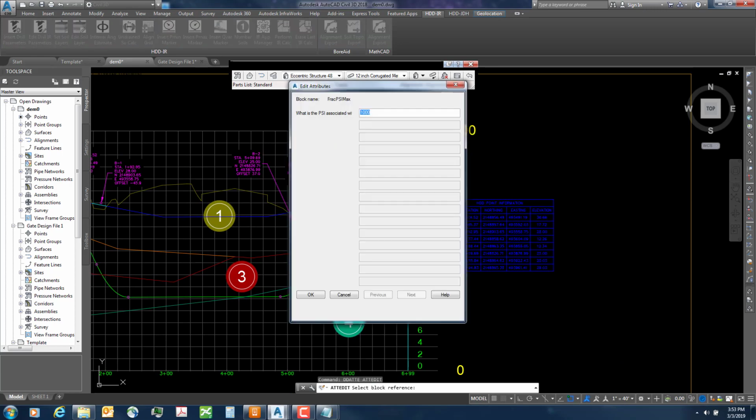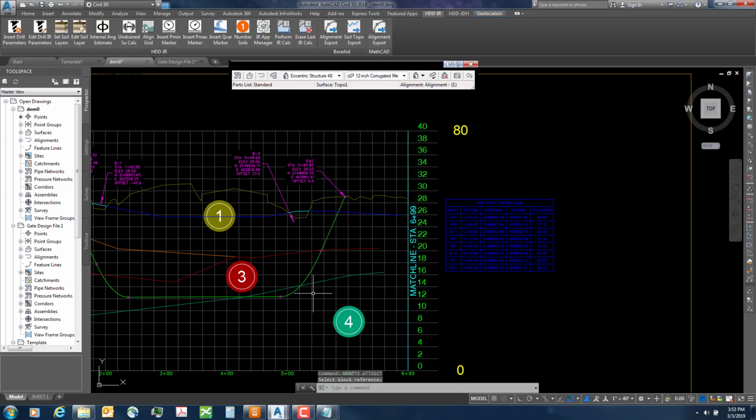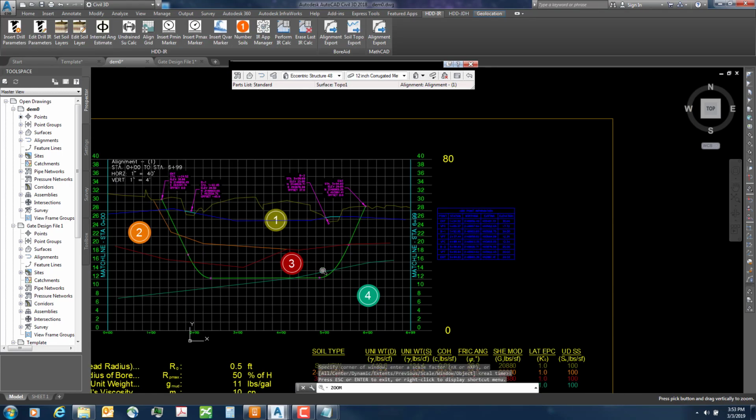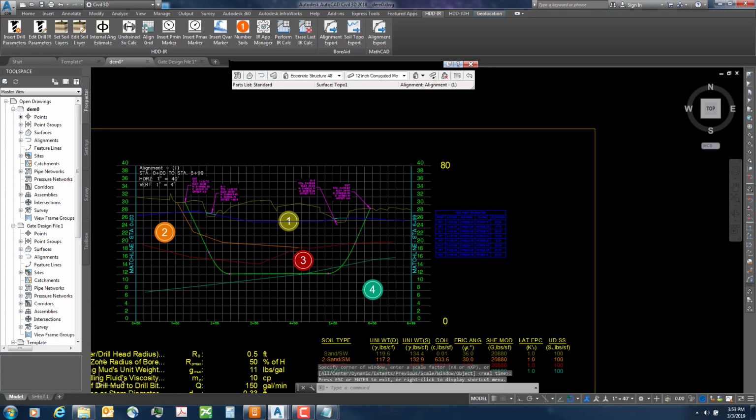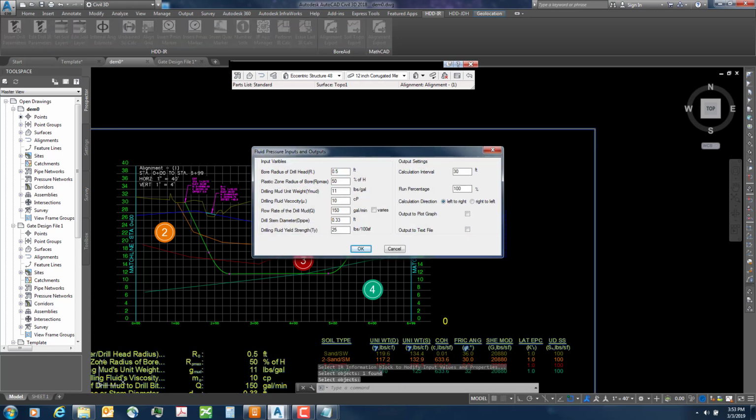We're going to set it to 80 psi. Let's go with 80 psi. So essentially it's creating a secondary scale over here on the right, where the bottom of the scale is 0 psi, but the top of the scale is 80 psi. So now I can come back into my drill parameters, and I can say, hey, I want to now plot the findings to a graph.